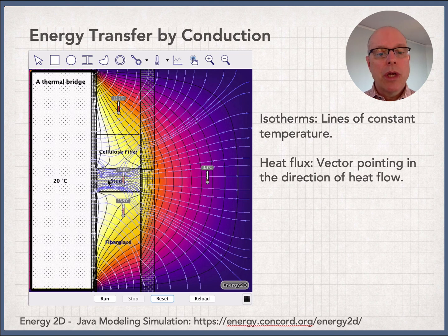Anyway, the thing I want you to notice is that when you add those lines of heat flow, you should really pick up on the fact that the heat comes streaming through the stud. So that's an example of a material being a heat bridge.